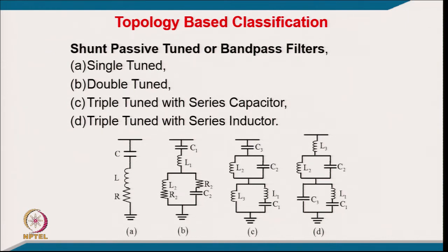Well, you are seeing another element here, a resistance. Normally this resistance is not kept separately. It is a part of the inductor, because no inductor can be made without some loss. This resistance represents the loss of the inductor, the resistive loss, because you are putting a winding with a large number of turns, which certainly have some resistance.